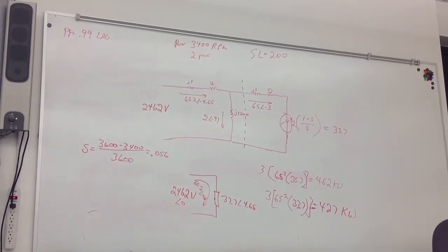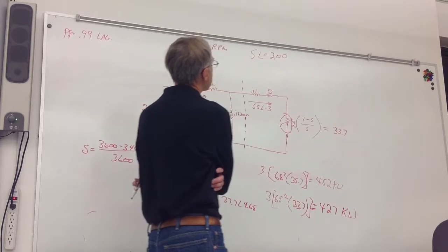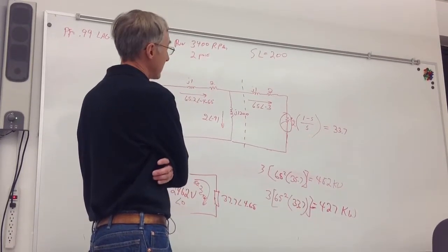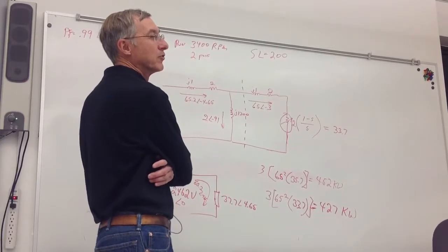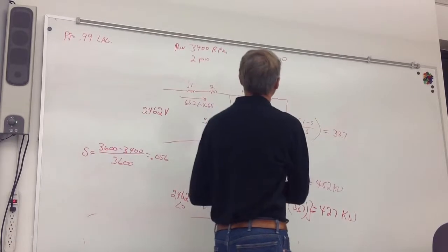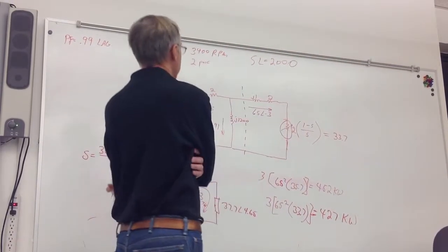Now if I want the shaft horsepower, or the power developed to the load, how do I get that? Subtract the losses. Which losses? The ones at the top of the board. I forget what they're called. Stray losses? Yeah. I made them too small. I'm going to change that. The stray losses for this machine will be 2,000 watts instead.